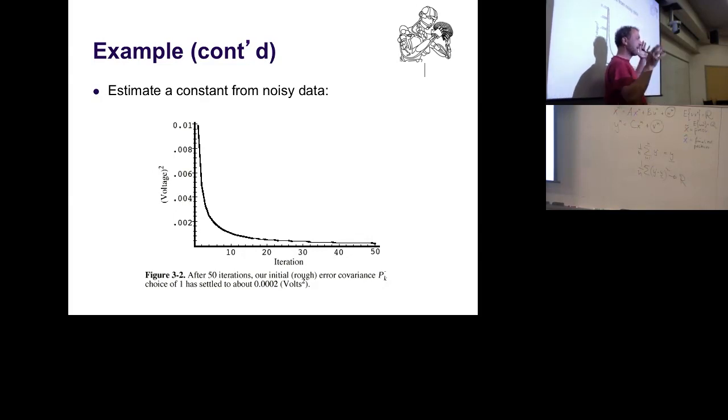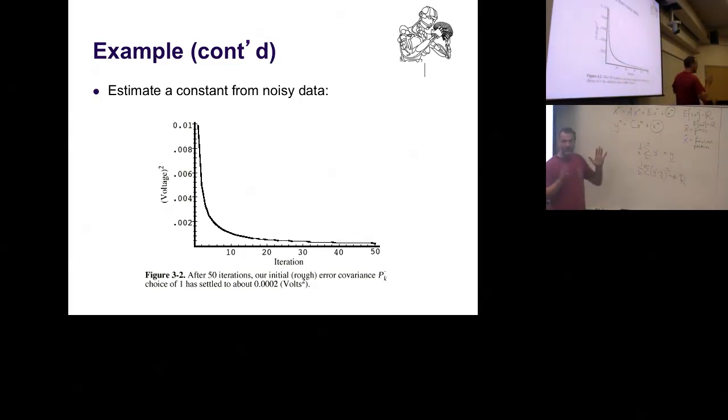Important message: Kalman filtering for linear systems is very similar to optimal control. It's derived from a similar optimality concept, just based on statistics. One thing which is interesting to note is that when you have linear systems, you can do Kalman filtering independent from deriving an optimal control law. The two of them do not interact, which is kind of cool. It's called the separation principle.